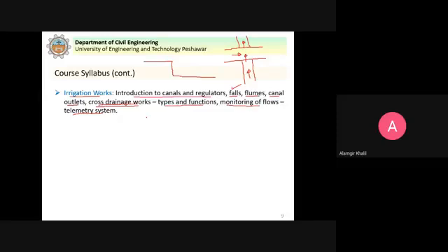And if we have so many points along the stream or river, so what we do instead is that we can develop a rating curve that you studied in hydrology. That is the discharge versus the depth of water at a gauge section.